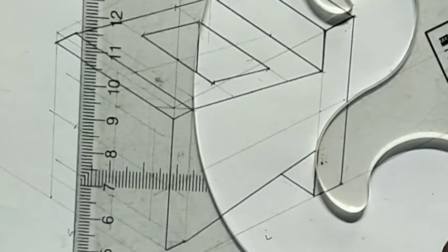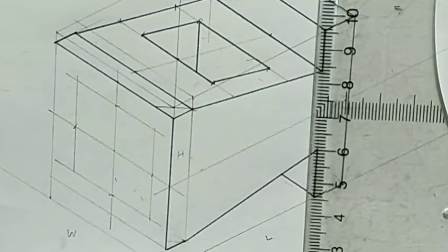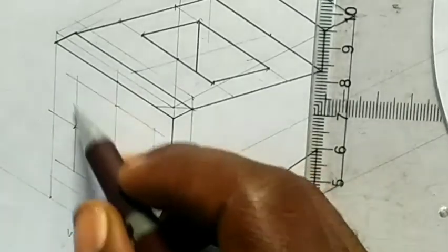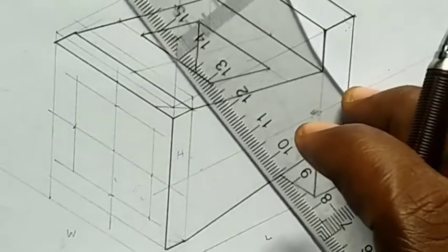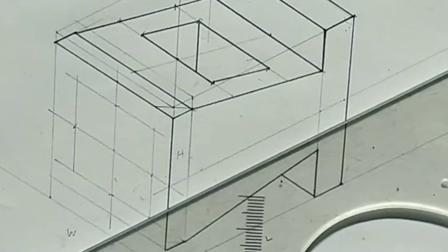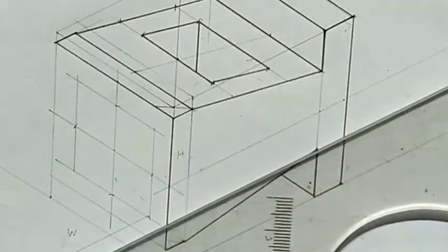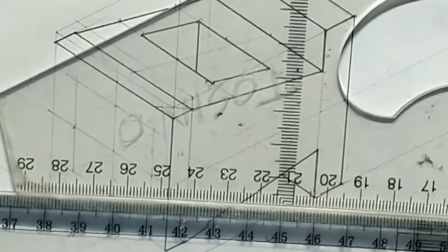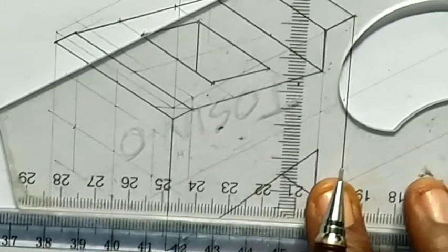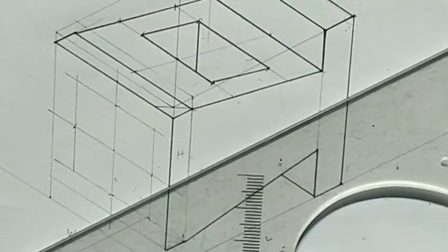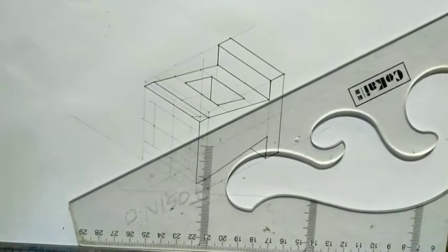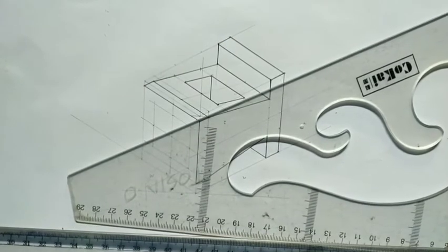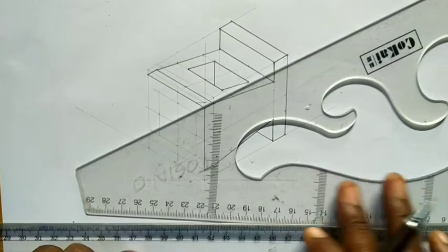One thing you need to understand is when you want to draw a circle in isometric, you need a perfect square that looks like a rhombus. So I've gotten my 4 corners here. So what will I do? I'm going to extend it forward. I will extend it forward like this. Remember that your set square is on the T-square, so don't forget that. So I'm moving it on the T-square, so I'll move it. Let me zoom it out so you see what I'm talking about. So it's moving on it. All good? So it's moving on it.